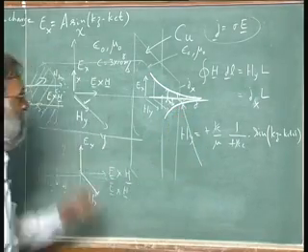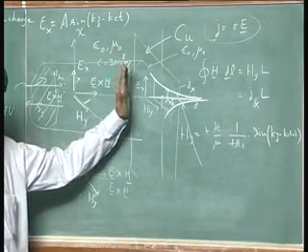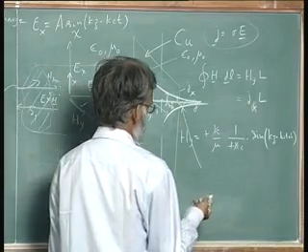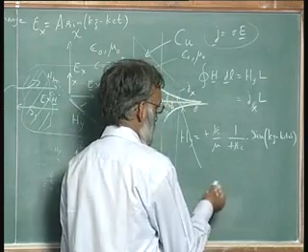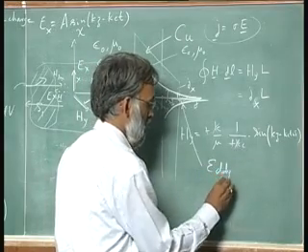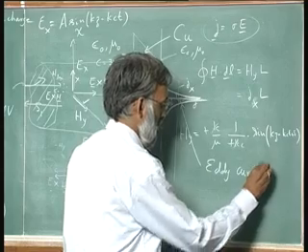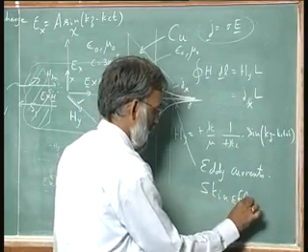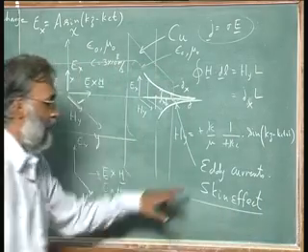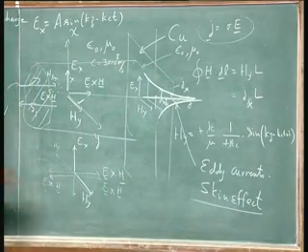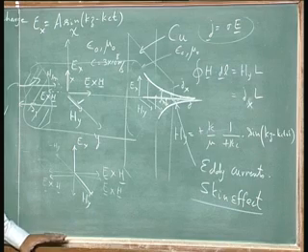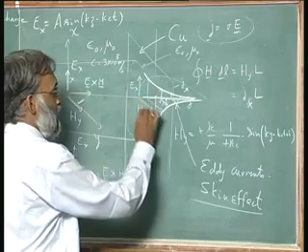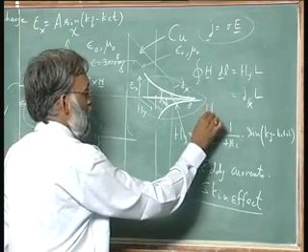This effect, whereby a wave enters a material and dissipates its energy, comes under different names. One name in which you see it is eddy currents. Another name in which you see it is skin effect. This is the common name that we usually give, the skin effect. And from our point today, the important thing to understand is this represents heat loss.